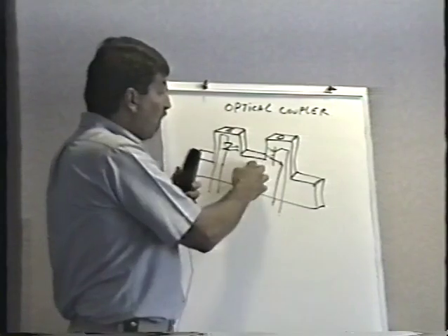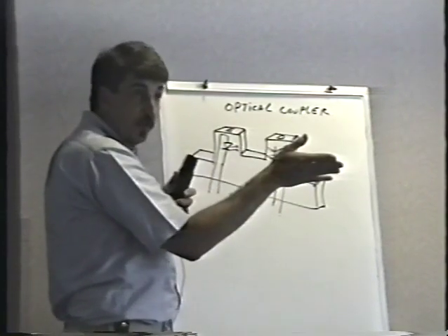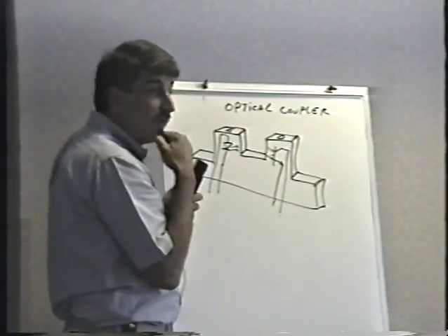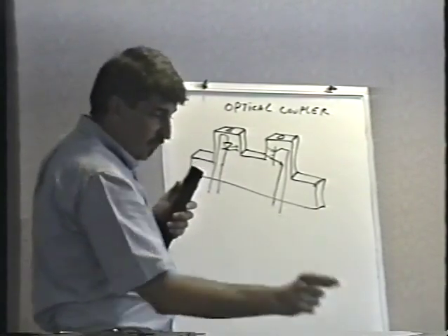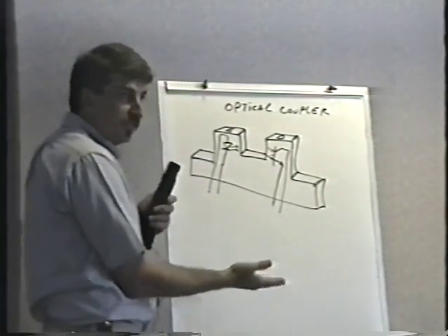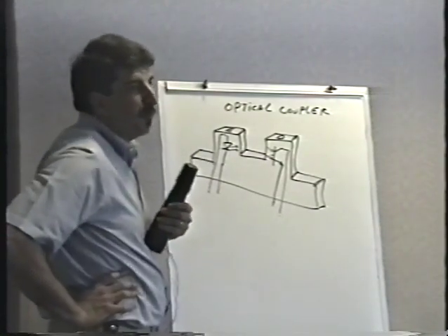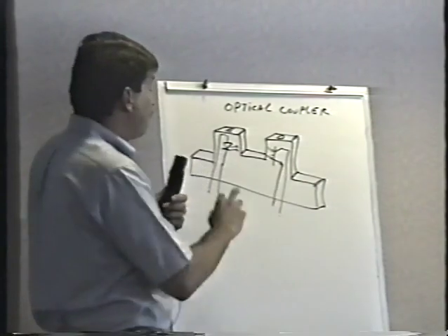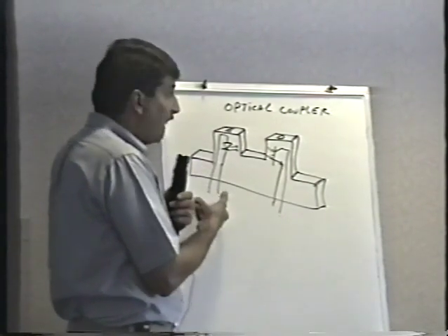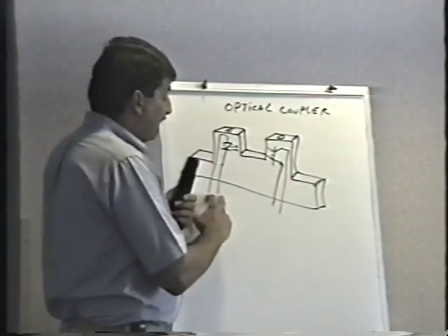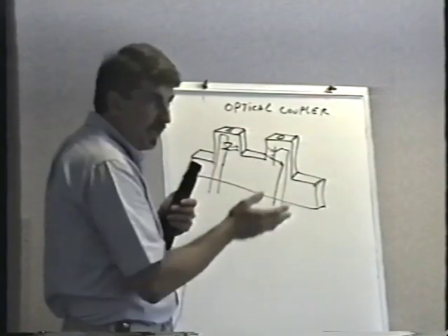Certainly if you had more than one of these units in a game and you could compare the two, that would be something you could do. But there's not a good test where you could have the optical coupler on your bench and just check it with a meter and see if it's good or bad. You can't test that diode with a meter. Not really. You get a junction drop of about 1.2 one way and open the other. But I've had them pass the junction test but not emit worth beans.